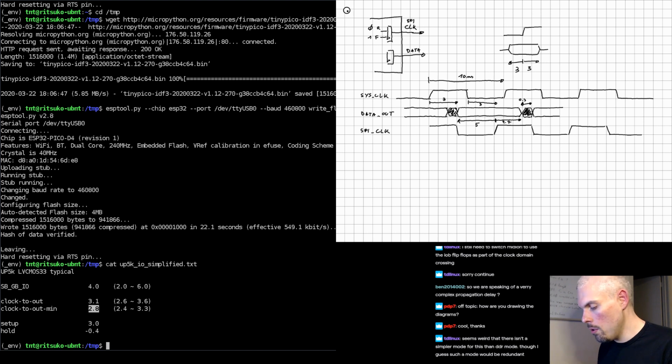So what you can do is use a different clock domain to generate your clock, and instead of feeding it the same clock as you feed the data, you use the PLL to generate a clock that's 90 degrees out of phase. On the iCE40, it's a bit annoying because the PLL is kind of limited and you potentially need it for other things. But in the ECP5, generating a 90-degree out of phase clock is fairly common. That's one option.